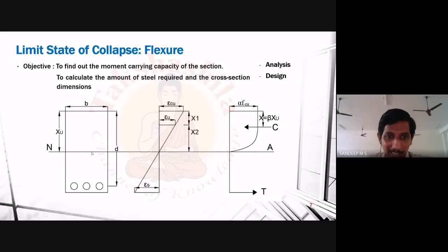In the other case, when we have an over reinforced section, what will happen? The amount of reinforcement is more. Let us assume that the reinforcement is more powerful. In this case, what will happen to the neutral axis? Neutral axis always stays with the powerful person. So once we have an over reinforced section, the neutral axis will shift towards the steel. I said this just to remember quickly; it is not actually like this, it is just a shortcut.